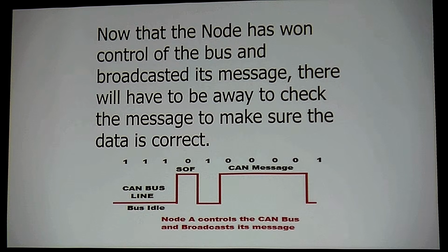Because you can't even tell, because so many different modules could need it. Depending on the situation the vehicle is being driven in, and what's happening, is how much the bus time is. So you can't calculate how long your latency is going to be. That's why you have X-by-wire stuff that's run on a clock, a master clock, where everybody has his own time, because I can figure out my latency as an engineer. It's safer. This works really well, but there's always a latency factor, where I don't even know when I'm going to get my message through.